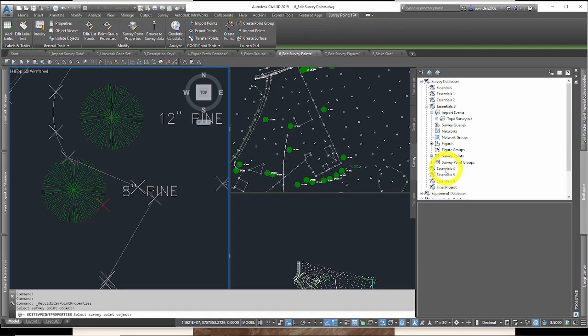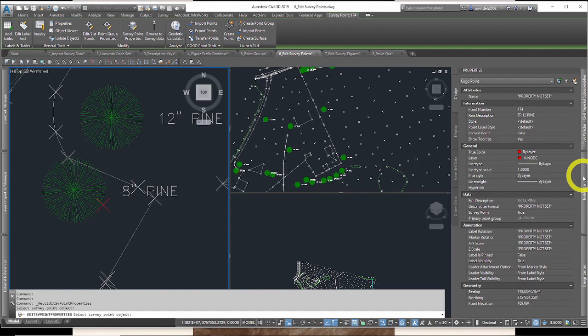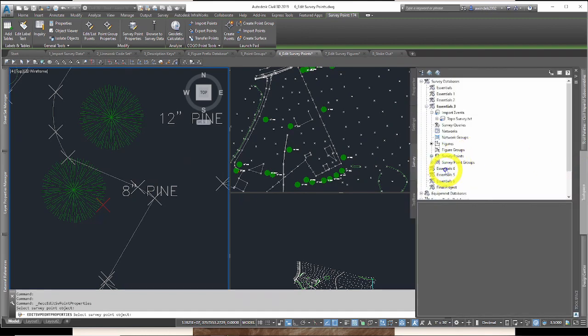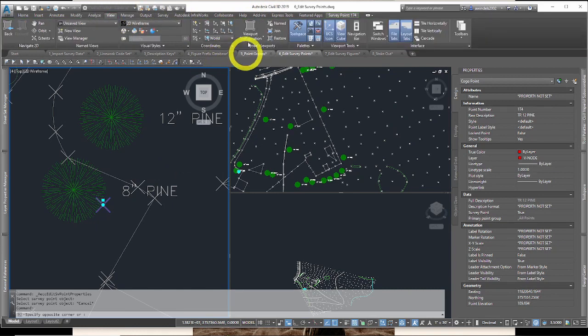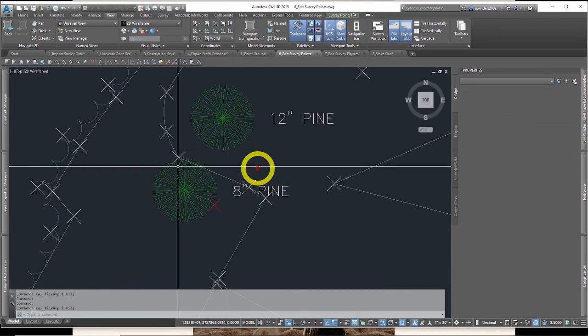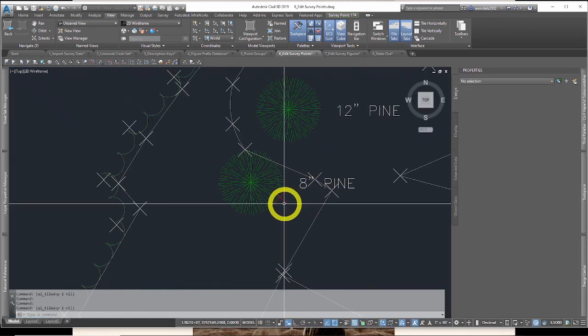I'm having nothing but problems with having this many files open, I think. I could maybe take a quick nap while I wait in between. That would be fun. For one, let me go back to hitting escape, and if AutoCAD doesn't make me take a nap again, I'm just going to go to configure viewport to 1. Let's speed things up a little bit that way to a single viewport. If you ever get a little bit bogged down in these drawings, it's always a good move. It gets a little bogged down with all 3 open on your resources.